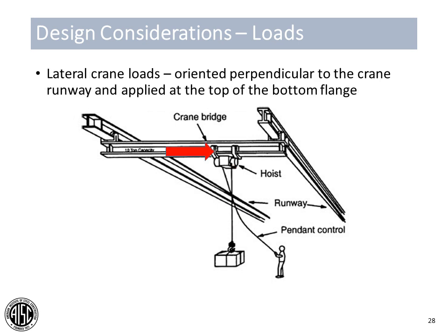There's lateral crane loads, sometimes called side thrust loads, which are oriented perpendicular to these runway members that we'll be designing. These lateral crane loads can be due to multiple effects. It can be the inertial effect of this hoist and trolley system traveling along the bridge crane itself, along the crane girder itself. It could be hitting this end stop on the crane.